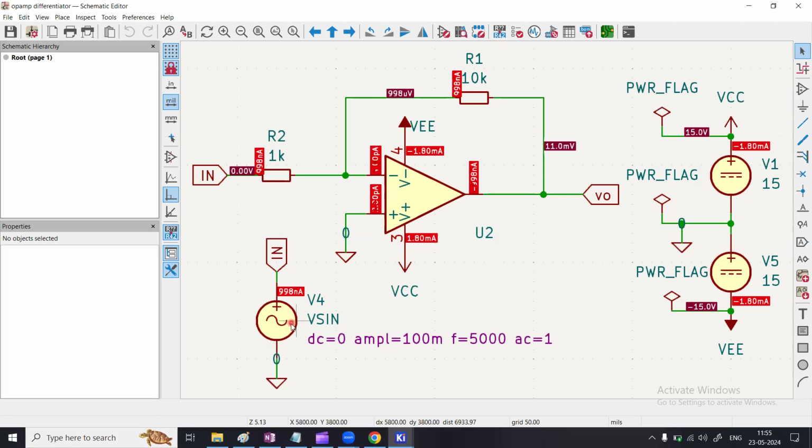So obviously you see now, the current supplied by it is close to 1 microamp, so it's quite less as compared to 1.8 milliamp. It's like 1,000 times lesser than this supply current. And that current is here, obviously 0 volt comes here. This is the DC potential, so here is 0 volt. Here is obviously 0 volt because you have biased the positive pin to the 0 volt.